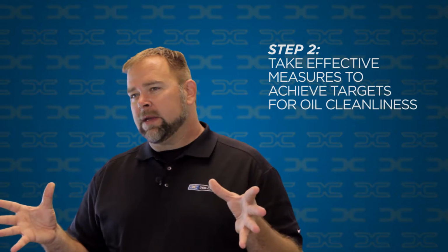The next step is to identify the things that we can do to actually achieve those targets. So we can basically look at 2 different approaches. We can either exclude contaminants or we can remove contaminants. And in many cases, we actually need to do both. But we should start by looking at ways that we can exclude contaminants because that is the simpler and cheaper way in most cases. And for a lot of machines, that's really the only thing we can do. For some machines, there just isn't a good way to remove contaminants other than just removing the oil itself from those systems.